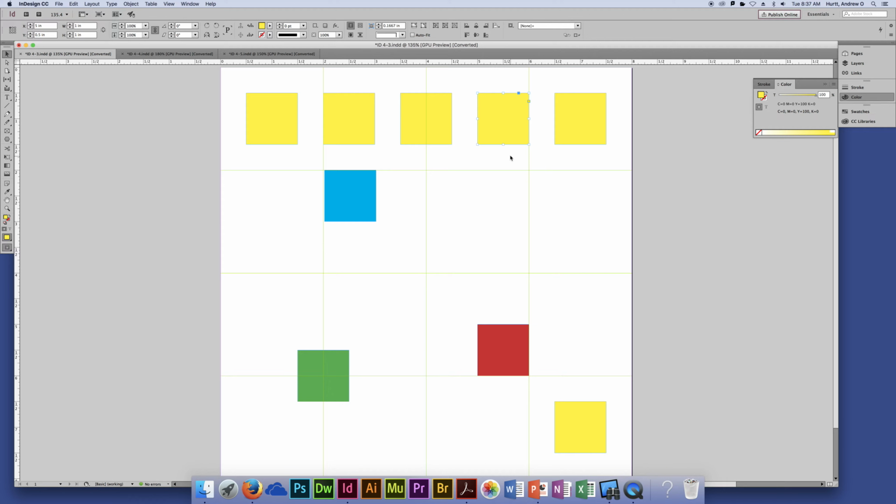Sometimes they can be quirky, but that smart guide can help when it sort of knows that you're aligning objects, you get those arrows that pop up that will show you that those gaps are even. So that tends to help distribute objects. But that live distribute helps a lot. Again, just holding shift and grabbing the resize handle. If you wanted to align these two objects and keep this distribution the same, it's super, super handy.